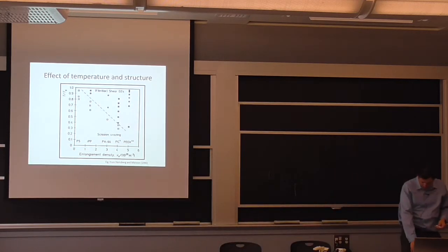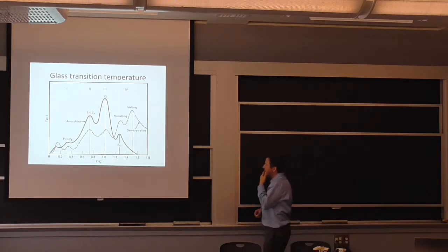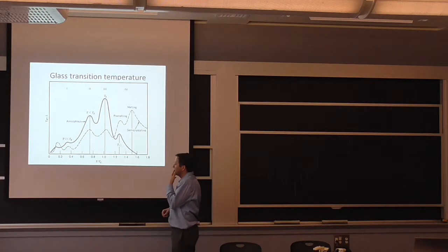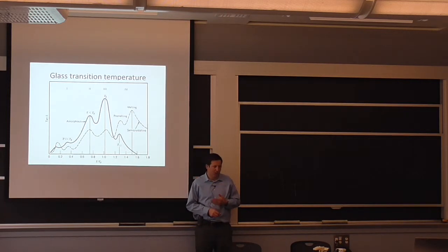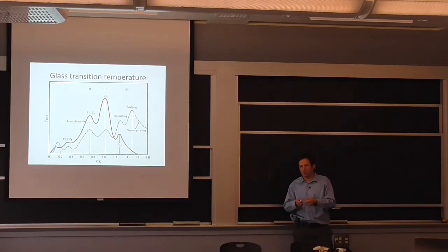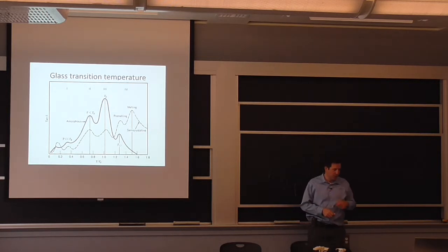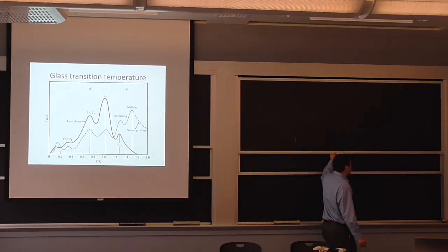Now, the glass transition temperature is essentially an indication of where you have a very rate-controlled, very high damping behavior. If you have a liquid, it flows at a certain rate. If you have a solid that is rigid, it will behave like a spring. In this intermediate zone where you have the glass transition temperature, it's really in between, and you have a delayed response. That's a way to measure it.